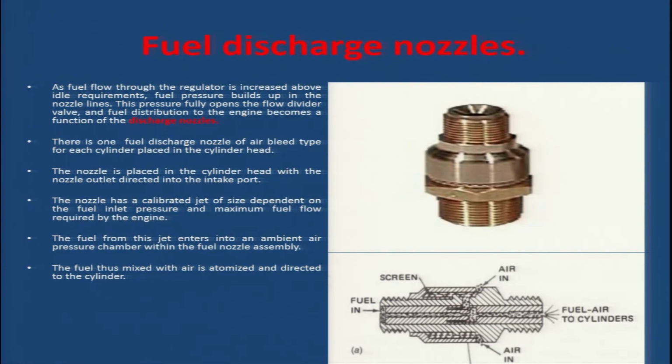nozzles. So we have seen in our earlier slide that the fuel flow divider was responsible for fuel distribution, and from the idle range up to a certain range, the fuel flow divider was responsible for equal distribution of fuel. Above a certain range, the nozzles take the responsibility of providing equal distribution of fuel to the engine.